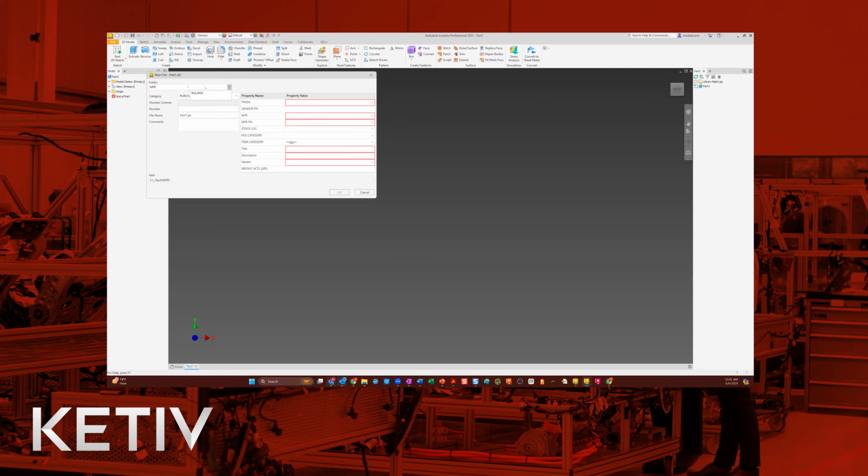So follow the same spiel as before. Part number, make this CL-12-F. Finish, we wanted that black oxide. So that gets selected. Common McMaster-Carr part number goes there. Manufacturer. Also just hit the R, that'll get you there quickly too from the pick list. Connect the CL-12-F to fill in here, stock location. Let's say this is at 115 now, file category. Purchase part, so PU takes care of that.